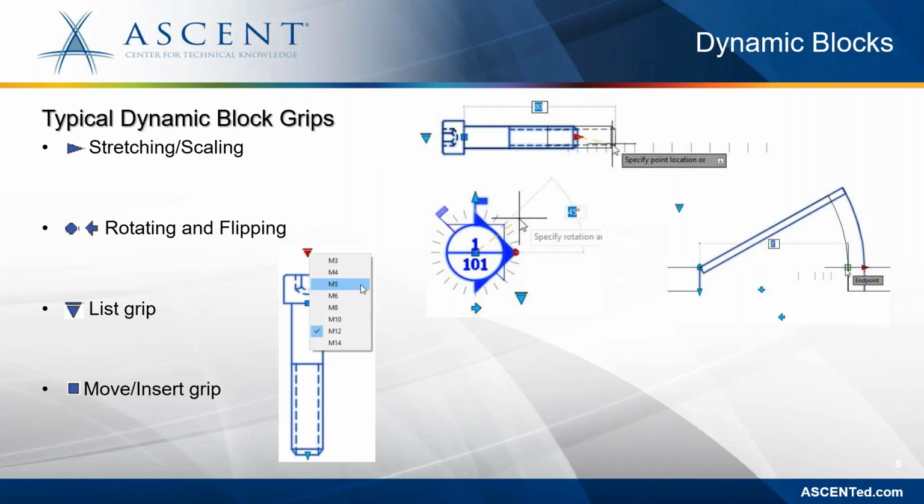Then the square grip, which is the move grip, is the most common grip available in blocks. It is also available in the regular conventional blocks, and it is the base point for inserting the block. It's also used to move the block in the drawing. So this concludes the first two objectives for the dynamic blocks.